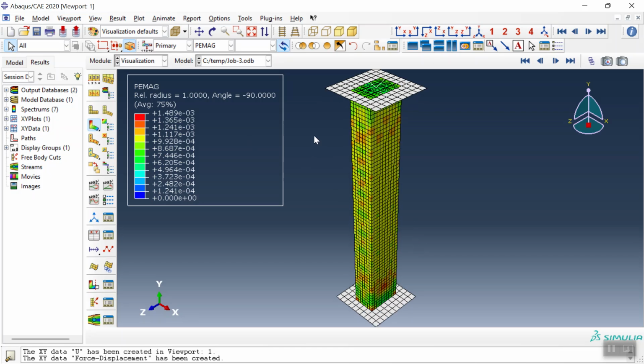And if you want to replicate this model, we explain everything in the model. For instance, the elastic behavior, the compression behavior of the smeared cracking, the tension behavior and tension stiffening, shear retention, failure ratio, all of these parameters are explained in the tutorial video.